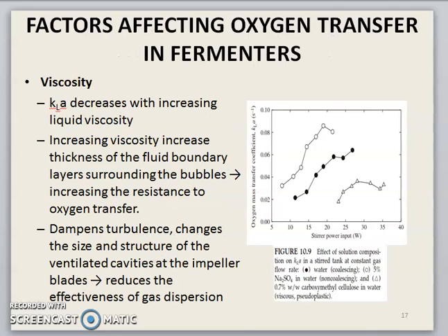The next factor is viscosity. The kLa decreases with increasing liquid viscosity. Increasing viscosity will increase the thickness of the fluid boundary layers that surround the bubbles, which increases the resistance for the bubble to transfer.